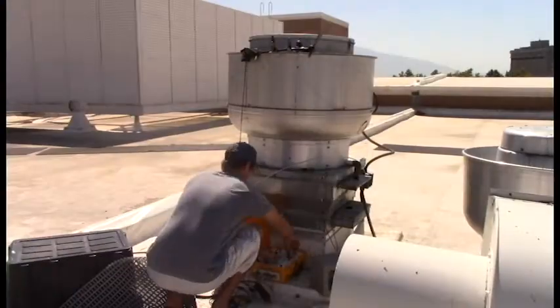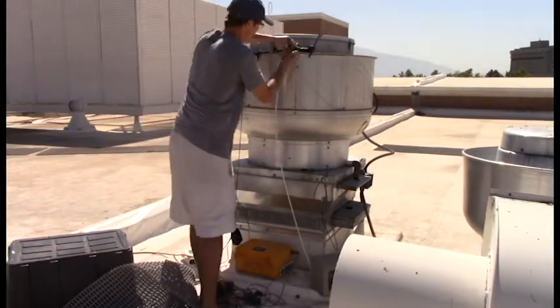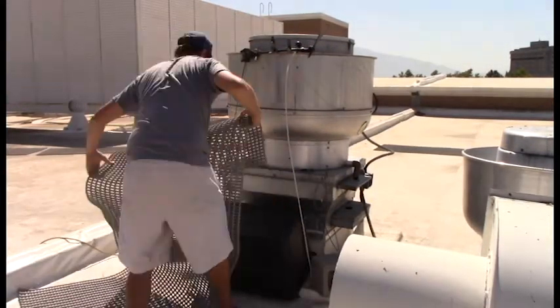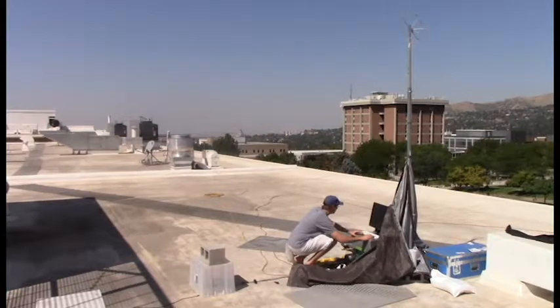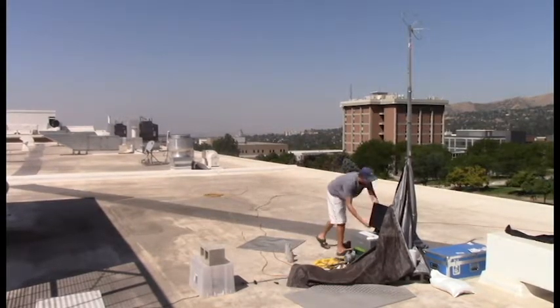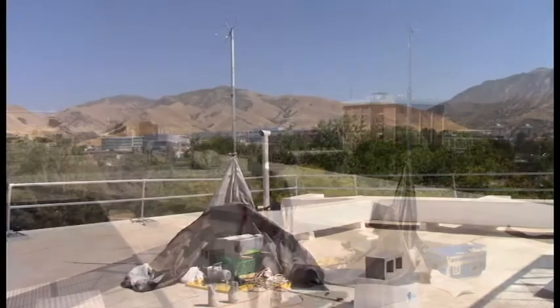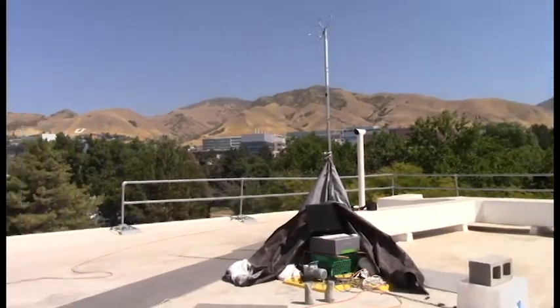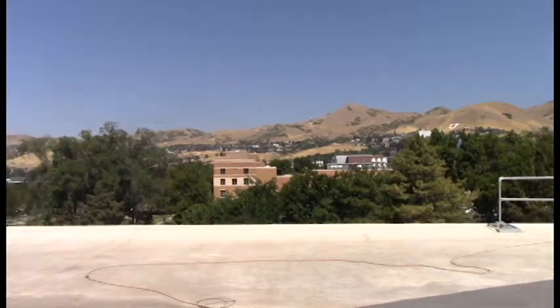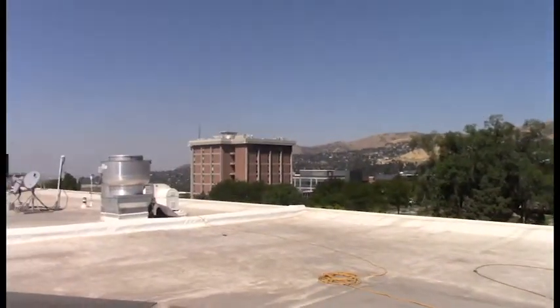We first set up a monitoring station using the LI-COR 8100 directly at the vent output. The detection tower using the Picarro spectrometer and 3D anemometer is then set up some distance away from the vent. Using these data, we were able to confirm that we were in fact detecting the fluctuation in emissions from the vent.